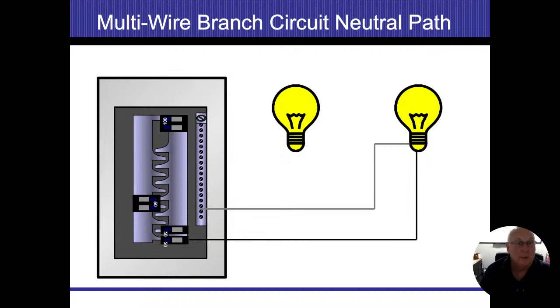So we're going to have another light bulb that goes on there. We're going to hook that up to our opposite breaker, all right? And I guess I also want to take a moment here and talk about that staggered bus bar that we're looking at inside of our panel. So you could see that the bar on the left is taking power off of the top breaker. The bar on the right is taking power off of the bottom breaker. And I'm talking about the main disconnect at the very top of this diagram, all right?